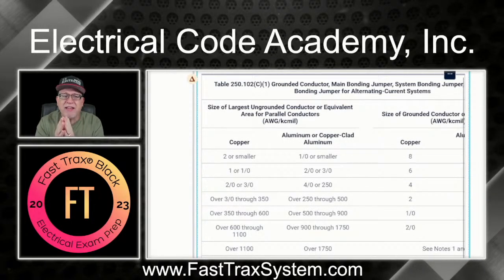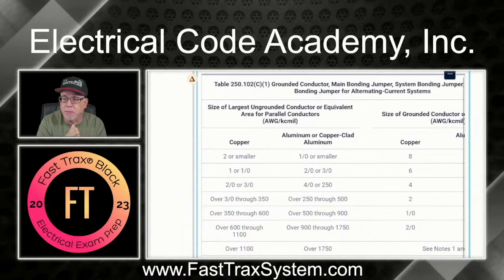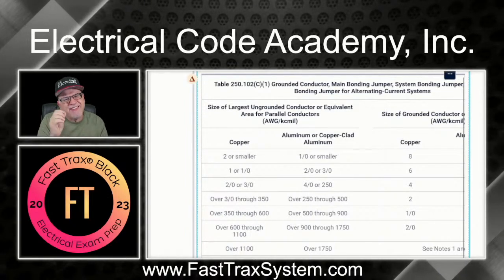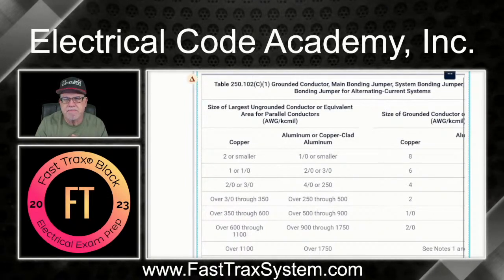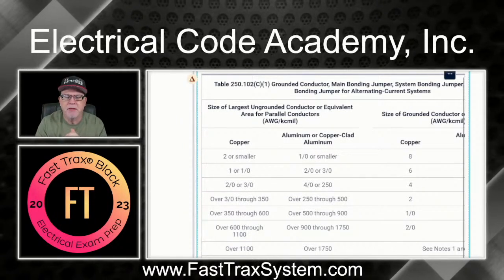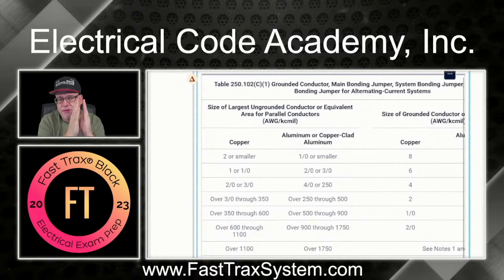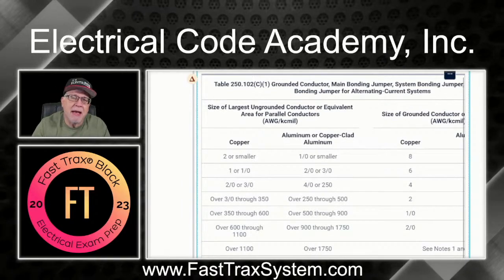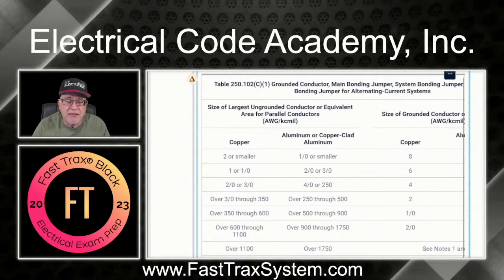We're going to take the largest ungrounded conductor from each set, which is, let's just take A phase, because they're both the same, they're running parallel. So we take the A's. Let's say we ran 2 sets of 350s, and it went through one raceway. Then that's going to be 350 times 2, because that's A phase, you have 350 for each. Add them together, that's the summation, and that becomes 700 kcmil.